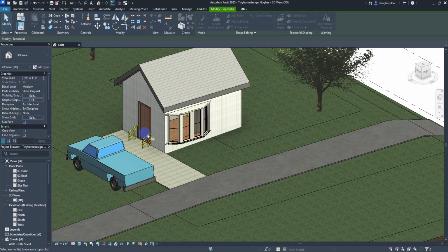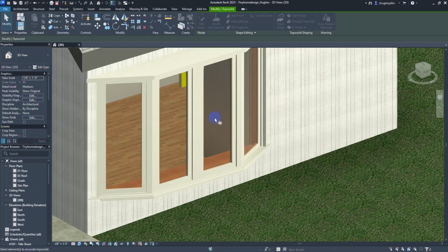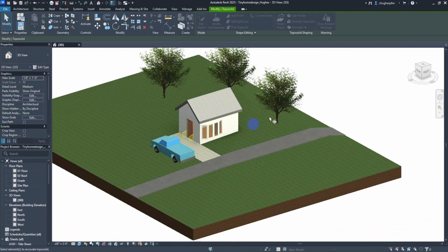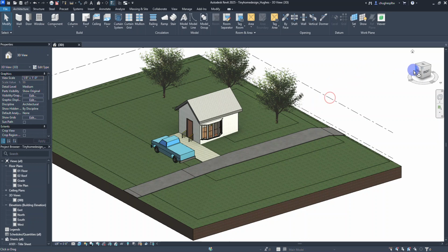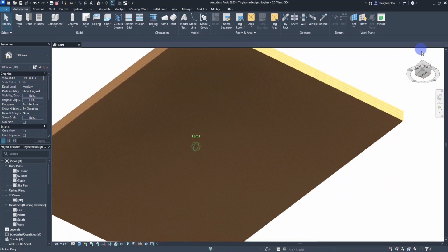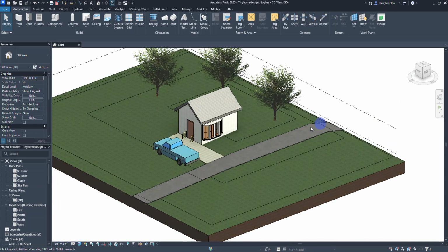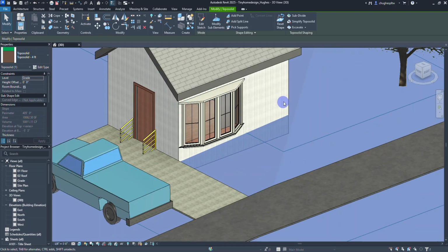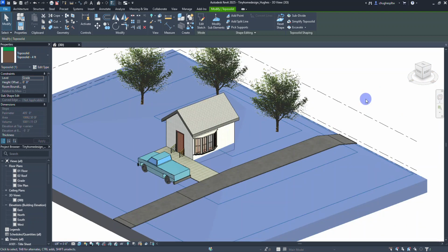And then it's going to see that when I select that floor, when I have that excavate option, I don't see the ground in there anymore. And if I say cancel, if I rotate down, I'm actually going to see that if I select the topo solid, I don't really have a cutout, but what I've got now is it's cut out, using the floor as a cutout around to be able to make that happen.